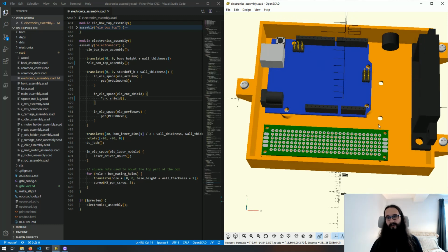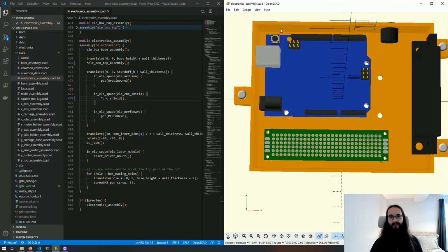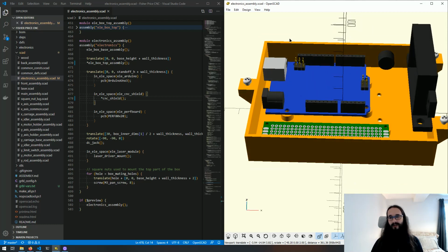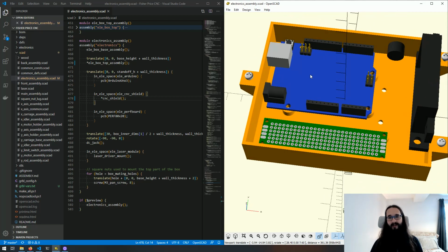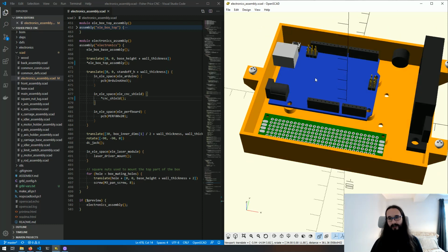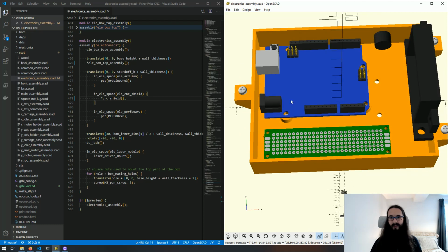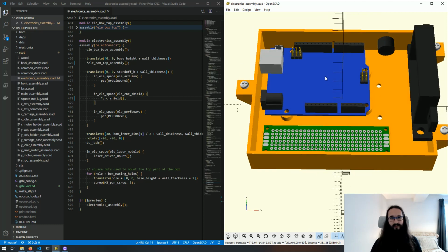When you do this sort of mechanical design, what you care about is where your connectors are, sort of user interface input. So here's the reset button, which is definitely not going to be accessible, but that's okay. I can just break out a separate panel mount push button for that. And then the physical connectivity stuff, like the standard Arduino pin header and the ICSP pins, and the general shape and vertical dimensions of the board.